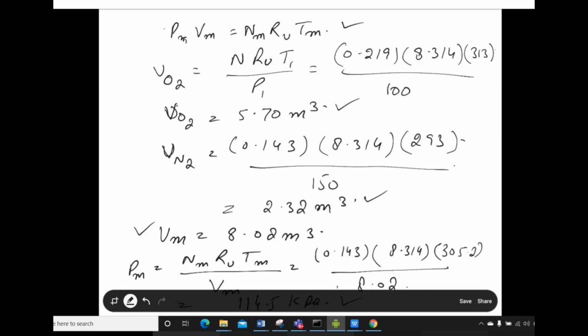That's why we do not have to go for delta H, because whenever we say that it will be equal to delta H, we say that the working fluid is transferred from one place to another. So here it will be equal to the change in internal energy. From here we can say Cv into delta T, and the mass is mentioned in your problem statement.